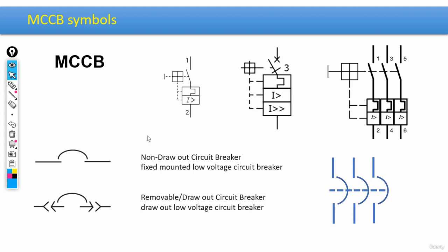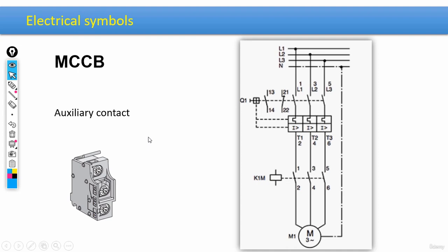Moving on, guys, there are some auxiliary features to these types of breakers. Like, for example, MCCB breakers actually have auxiliary contacts. Alright, let me try to give you a further elaboration on this. Let's say, for example, the switch is actually on here. Let me write it down. In this case, the normally open contacts that we have would be closed, and, exactly in reverse, the normally closed ones would be opened. And yeah, basically this could be counted as an auxiliary feature that we have in such breakers.